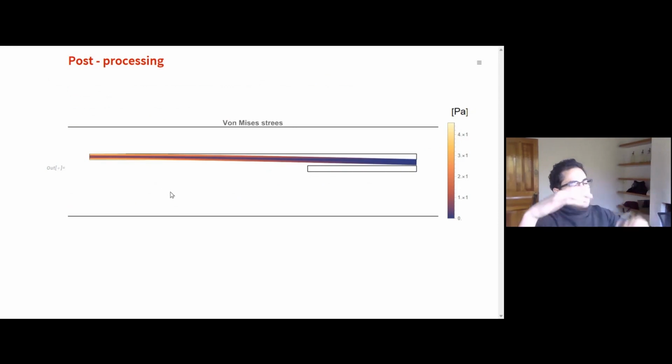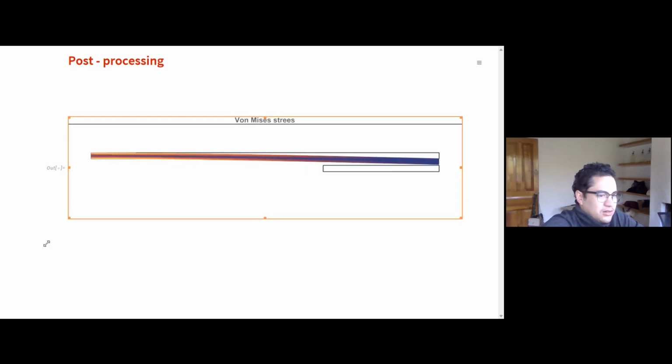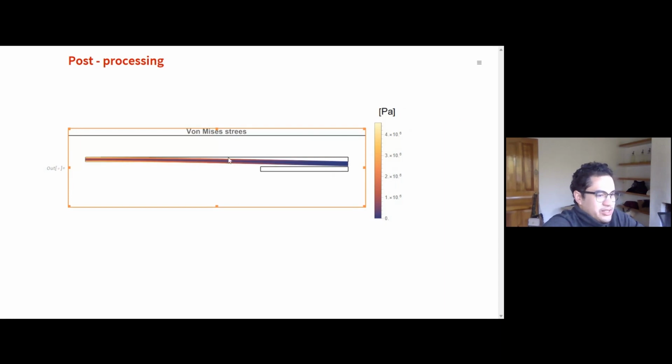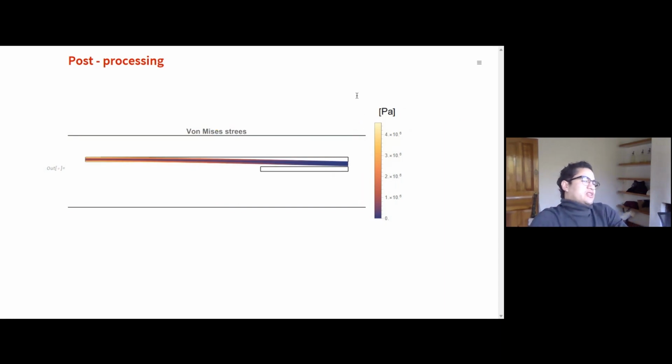In solid mechanics, you can do a lot of post-processing: compute stresses, deformations, strains. In this case, we computed the von Mises stress, which is the result shown in the article, and they match what is given in the article. So we can see here the distribution of the von Mises stress in the deformed top electrode. We can see already the distribution and the deformation, and the maximal displacement that we get with these characteristics. So you can see that the electrostatic model can be coupled with different physics, for example, solid mechanics. And well, you can do many things already with just the electrostatic equation.